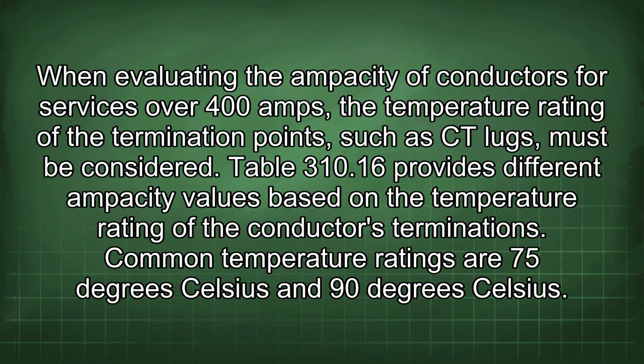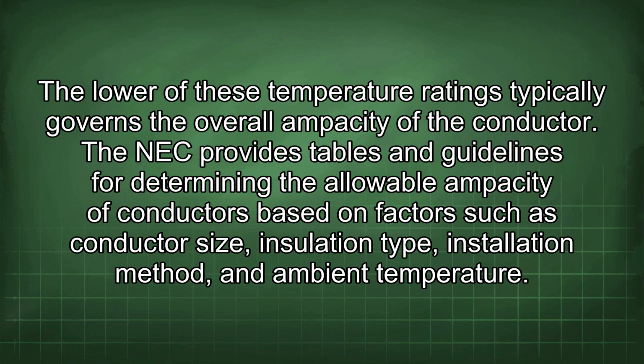When evaluating the ampacity of conductors for services over 400 amps, the temperature rating of the termination points, such as CT lugs, must be considered. Table 310.16 provides different ampacity values based on the temperature rating of the conductor's terminations. Common temperature ratings are 75 degrees Celsius and 90 degrees Celsius. The lower of these temperature ratings typically governs the overall ampacity of the conductor.